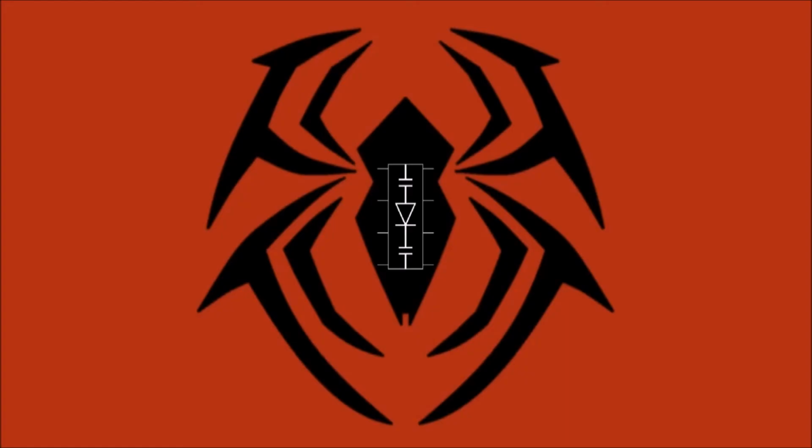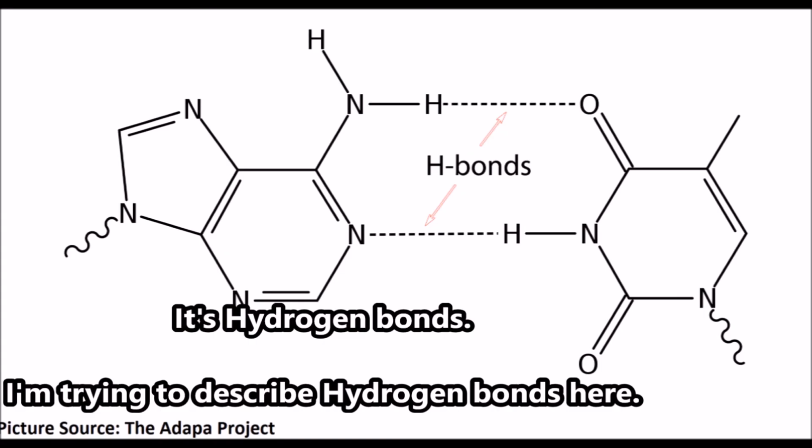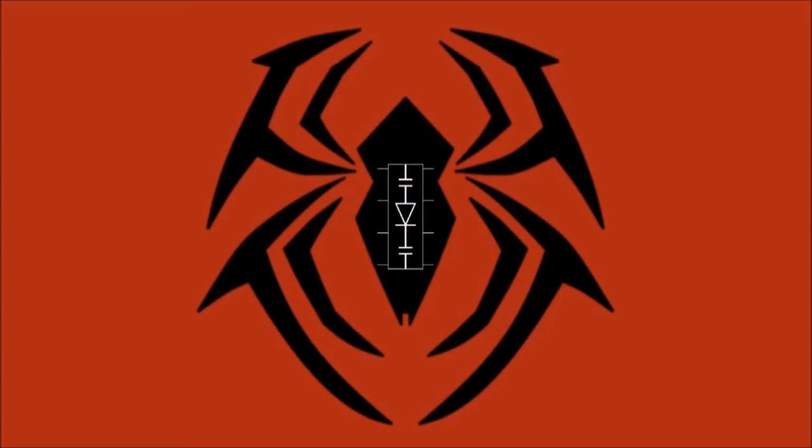I've already talked about clogging a little bit, and that may increase with what I'm about to talk about. But something I really want to cover here that's actually really interesting and useful when considering your fluid and appropriate spinneret is the self-siphoning property, which I said I would explain in this episode. Without getting too in-depth, basically the self-siphoning property is a property of a solution, where the molecules in solution actually have a slight interlocking effect with each other's outermost atoms, and as such the fluid becomes somewhat elastic and incredibly cohesive.